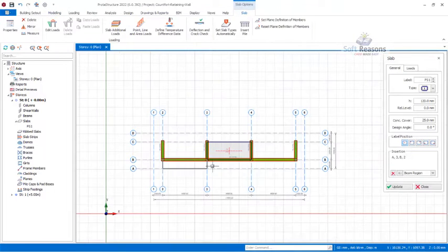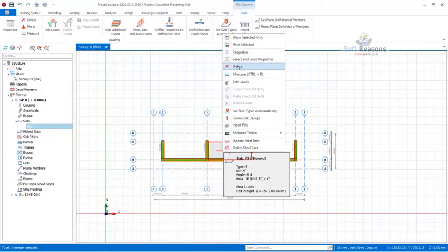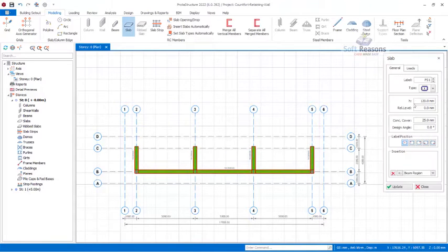From the slab dialog right there, we have this placed. In this case you don't use an ordinary slab, you have to use a cantilever slab for the modeling of the base of the footing. So click on the slab again. Over here, slab type is going to be 12. The slab thickness is going to take the depth of the foundation, so it is 400. After which the concrete cover is going to be 50.